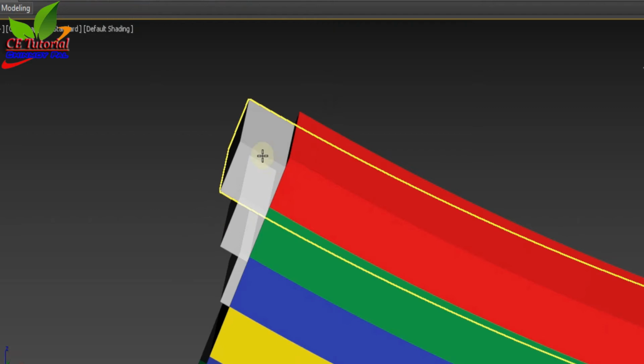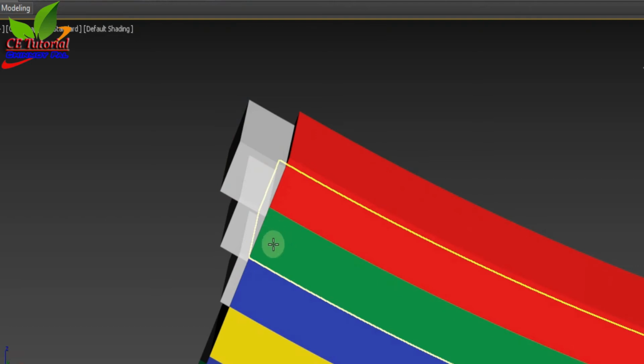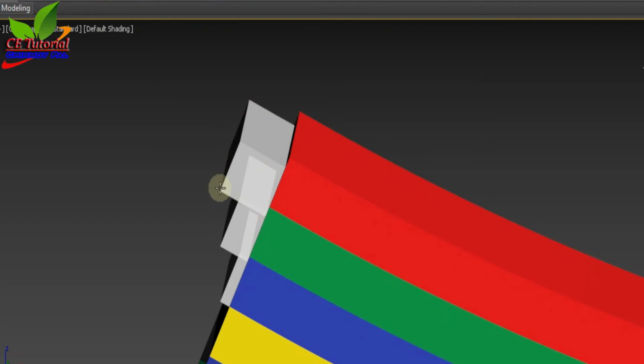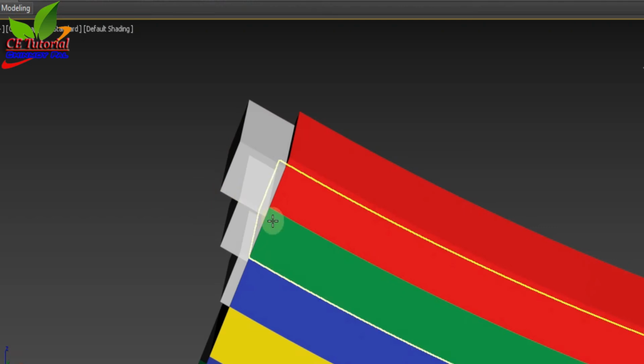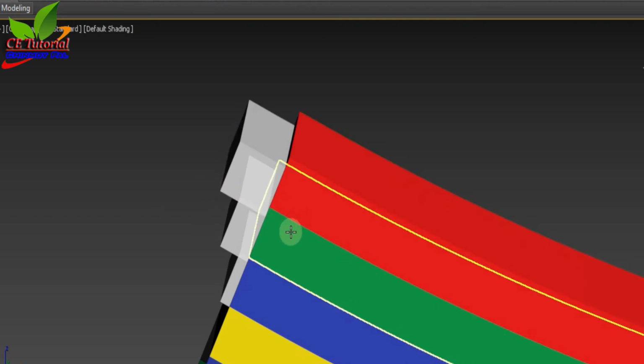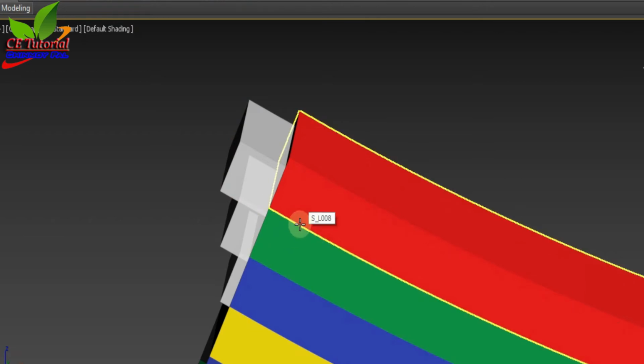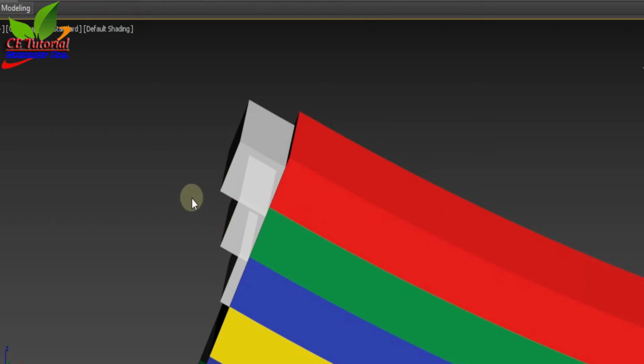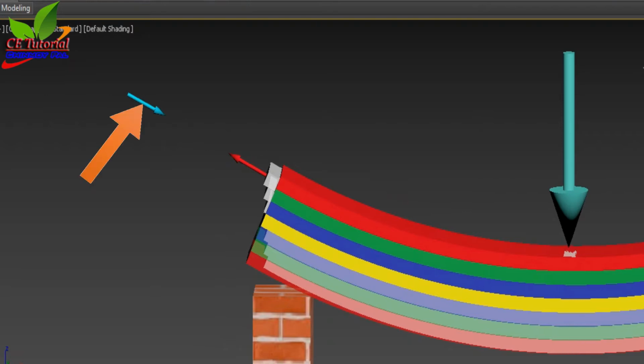The topmost fiber of the beam gets compressed because the lower layer is trying to keep the end of the upper layer with its own end, as they are not acting individually. We can say that virtually a compressive load is being applied along the longitudinal axis of this particular layer.